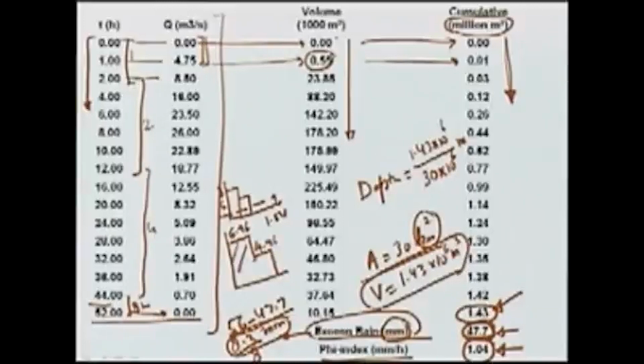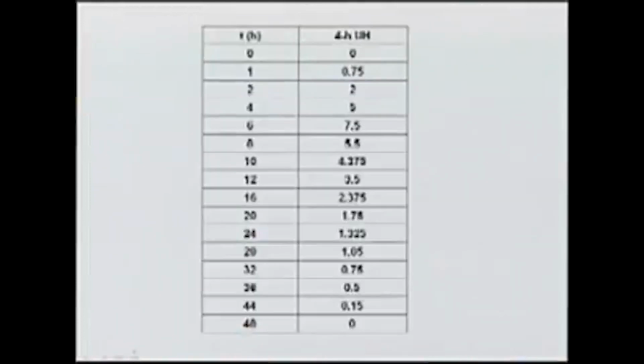So, this is the effective rainfall. Four hour of intensity 6.96, another 4 hour of intensity 4.96. So, in this way we have obtained the phi index, which tells us that effective rainfall intensity for the first 4 hour period is 6.96 or almost 7 millimeters per hour, and for the second 4 hour period it is almost 5 millimeters per hour.